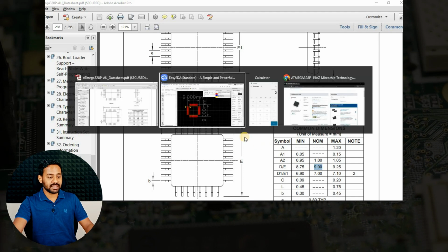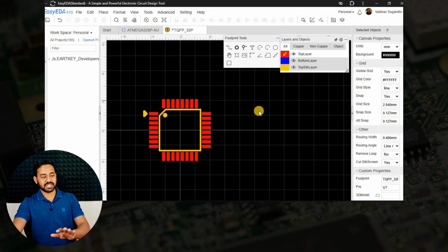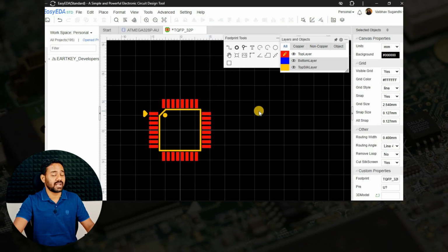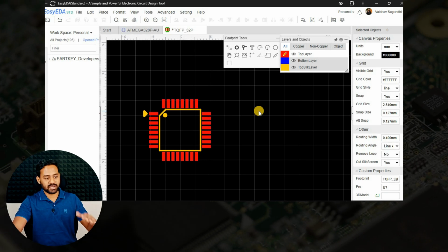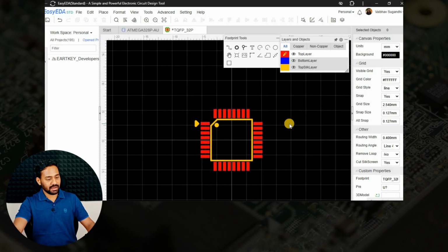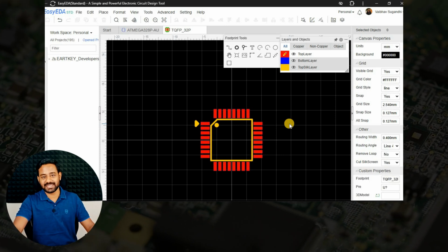If you maintain this distance on both sides, then whatever aesthetic changes or pad differences you make are not going to matter at any cost, because it's your personal choice. So this is how the entire TQFP SMD quad pin IC footprint is to be designed.